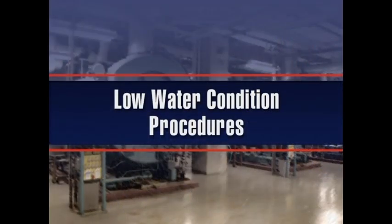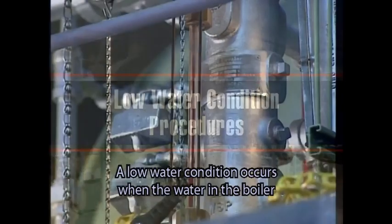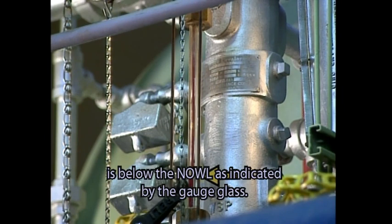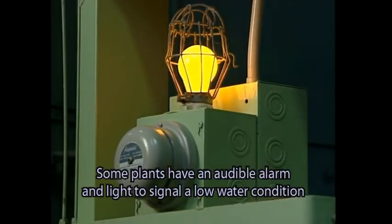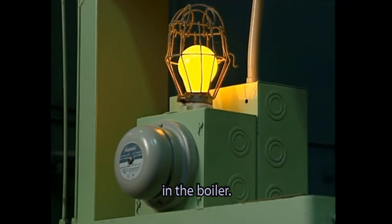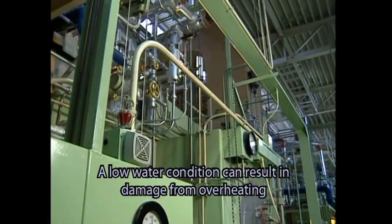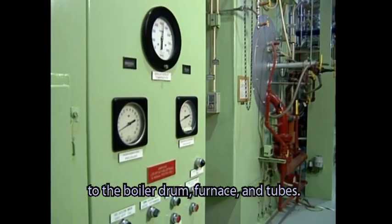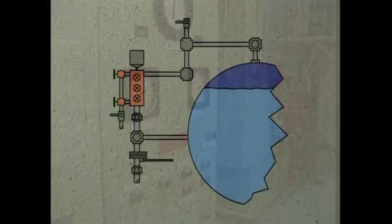Low water condition procedures. A low water condition occurs when the water in the boiler is below the NOWL as indicated by the gauge glass. Some plants have an audible alarm and light to signal a low water condition in the boiler. A low water condition can result in damage from overheating to the boiler drum, furnace, and tubes.